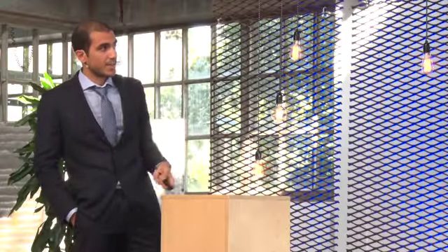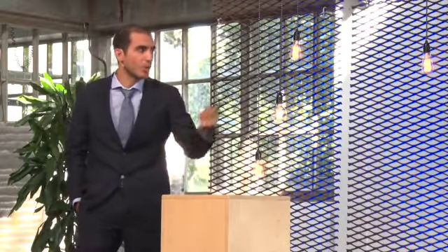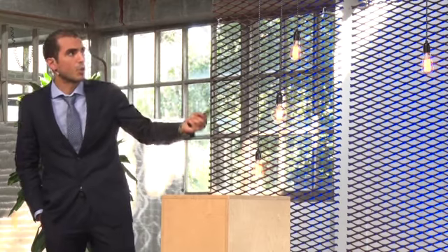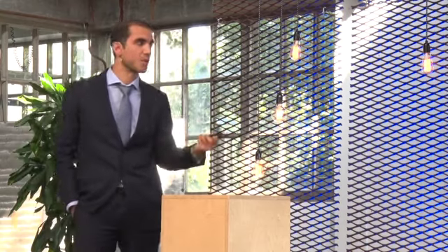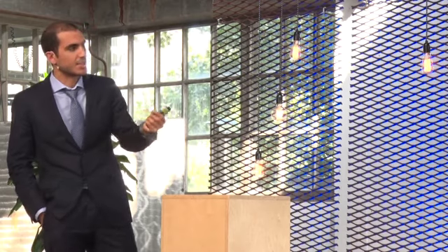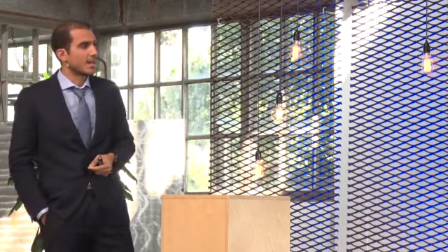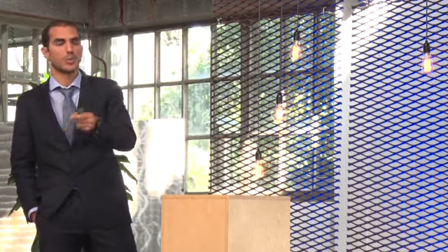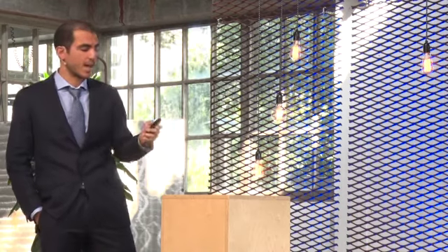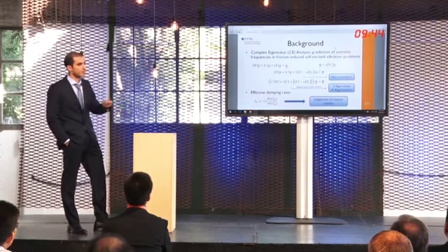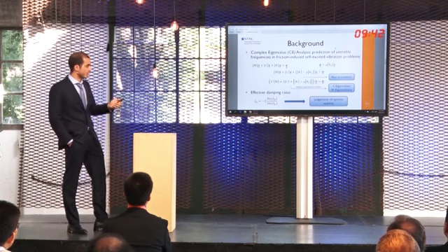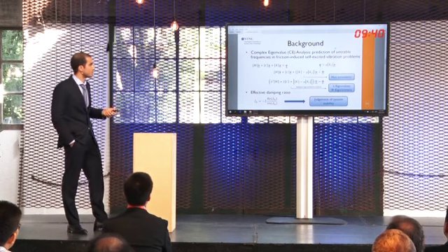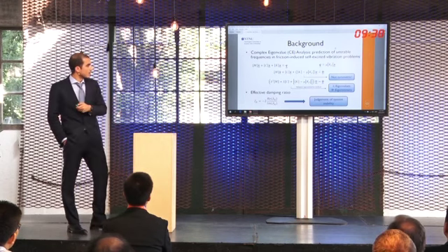After we have gotten the eigenvalues of the system, we can define what is called the effective damping ratio, which is a parameter that is used to relate to the system stability. If this parameter is negative, then that particular mode will be unstable, and therefore it will be related to high amplitude vibrations of the system, and therefore it can be correlated with corrugation formation.